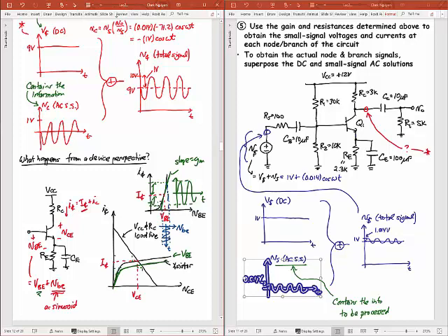And then up here I'm going to have another curve that's going up like this. And this curve up here is for VBE, the large signal VBE plus little VBE. Okay, and this curve down here is for that same DC bias VBE minus little VBE. Okay, so I have those two curves, and to really do this correctly, I have to get the intersection point here for these curves, which ends up being close to what I had before.